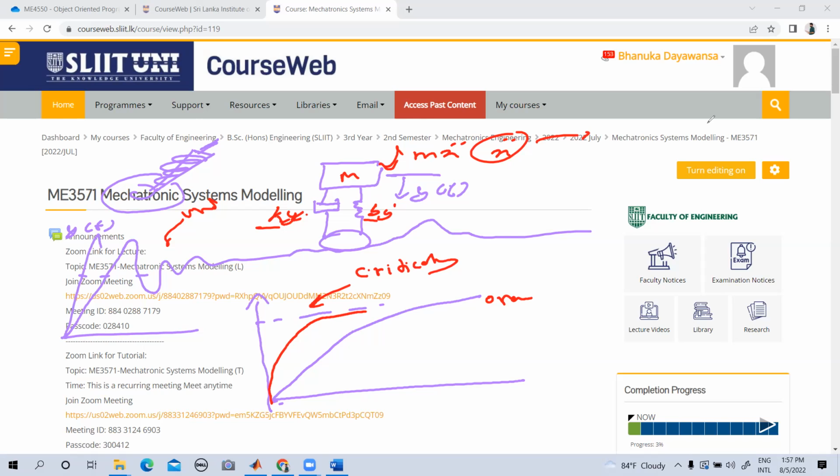We don't actually like to solve differential equations in the time domain. So what we do is convert the model into the S domain, or the frequency domain, using a tool called Laplace. We convert the second order system into the S domain, and we have an algebraic format, right? We don't have these derivatives and all this, right?